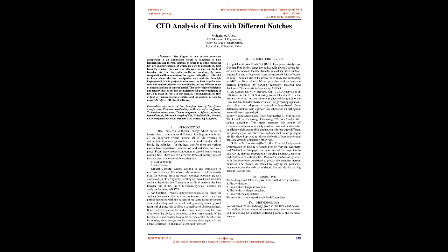stresses. In order to cool the engine, the fins are another component which are used to dissipate the heat from the engine. Fins are generally used to increase the heat transfer rate from the system to the surroundings. By doing computational flow analysis on the engine cooling fins, it is helpful to know about the heat dissipation rate, and the principle implemented in this project is to increase the heat transfer rate.